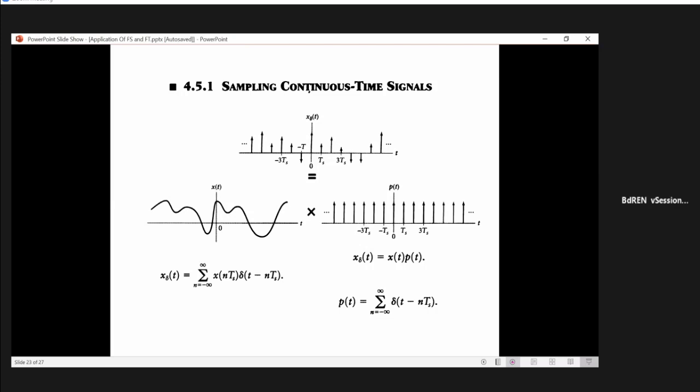The thing is that, when we have our signal present in continuous time, sometimes your signal may appear inherently discrete, but in most cases, your signal will be continuous in time. But if you want to process it digitally, you have to make it discrete. After discretization, you have to truncate or quantize your signal to finite levels. Then you have to code it by using some sort of coding technique.